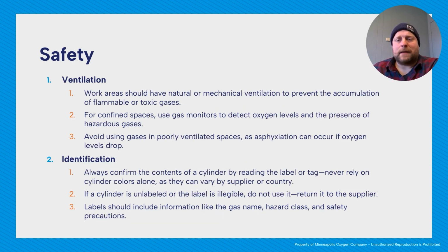Ventilation, we've got to make sure we have good ventilation to prevent accumulation of flammable or toxic gases. In addition, in confined spaces, we have to make sure our oxygen levels are good. Something like argon, which is inert. Argon is not poisonous. It's not like you breathe it in and you're going to start choking or something like that, but it is heavier than air. So if you're breathing in a bunch of argon, or you're in a depression or a lower area and you're welding, the argon will eventually push all the oxygen out, depending on how long you're in there.